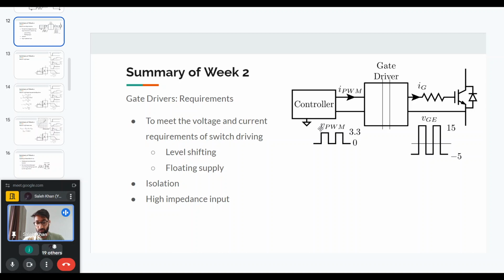So first of all, the question was about MOSFETs, and I think the same is the case with your assignment as well. So you have to take into account whether it is talking about MOSFET or IGBT. And then even in MOSFETs, for SiC MOSFETs, normally now we use negative voltage, but for low voltage Si MOSFETs, it is not needed that we give a negative voltage.